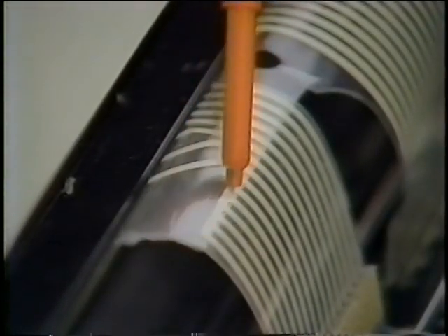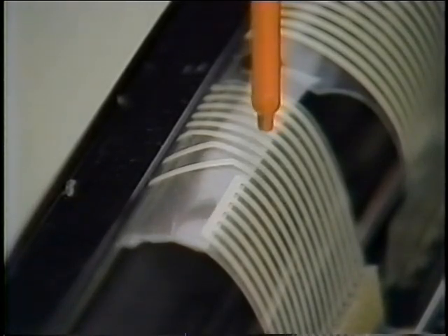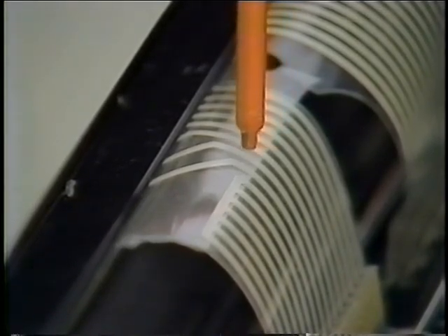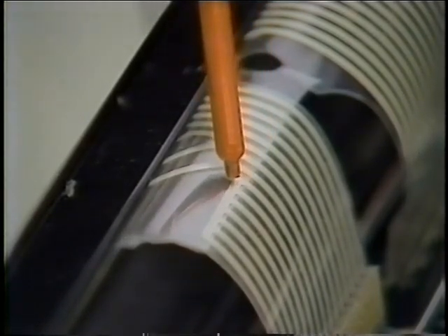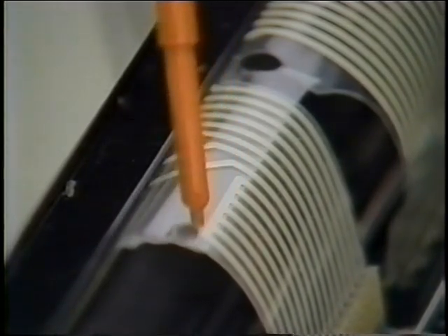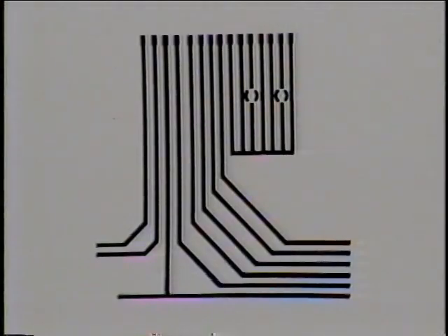These are the keyboard ID lines. These lines are connected to pins 9 through 15 of the J2F connector on the function board. The electronics uses the ID lines to identify which keyboard is installed on the machine. The function board supplies 5 volts DC to pin 9 of the J2F connector and looks for the presence of 5 volts DC on pins 10 through 15. By changing the combination of pins on which the function board finds 5 volts DC, the keyboard ID is changed. This is accomplished by opening some of the ID lines by punching a hole in them. The ID holes are punched during manufacturing.